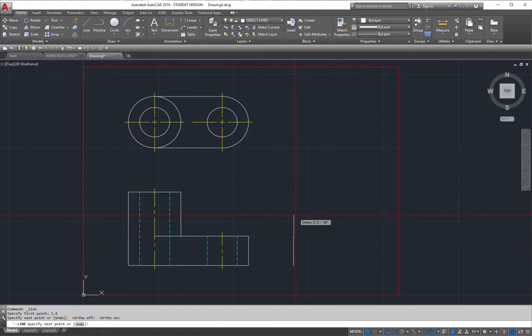And if I also needed to go all the way to here, I can just go there, place my cursor right here, and slowly move. For some reason it's not working, but look, go right here, and it's going to match this point, and I click there. And at this time I can just go right here, and I would know what my distance is if I looked at my actual exercise. But if I don't know, I can pause right here and say, okay, exit there, and I am going to actually draw my miter line, my 45-degree angle line.